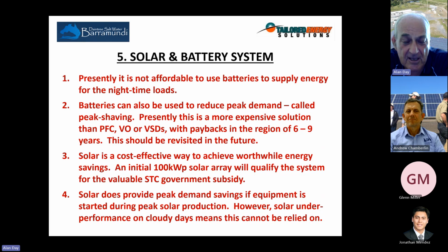We can't achieve that. So the first thing you'd say is batteries are nowhere near at the kind of cost where you could use them to support nighttime loads. But you can use them in a demand response mode, for peak shaving. So we're looking at doing this at a workers' camp just down the road from us, where we can shave the top off their peaks in the evening and get them quite a good saving for quite a small battery. So that actually is going to give them a very good payback.